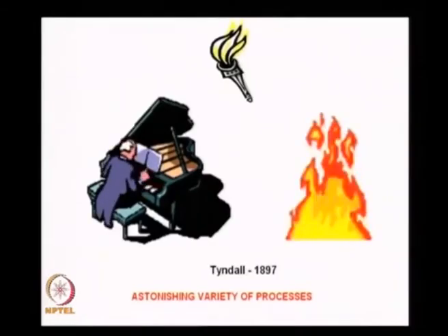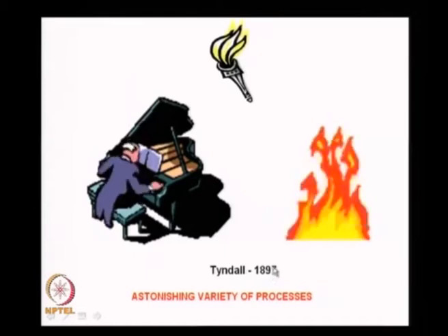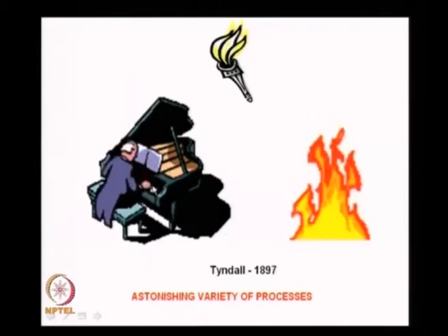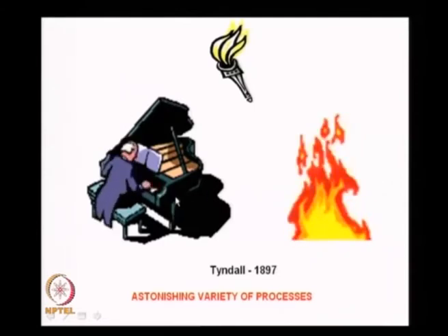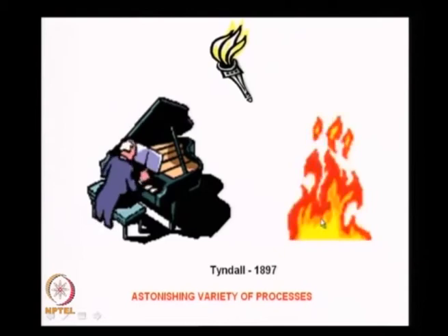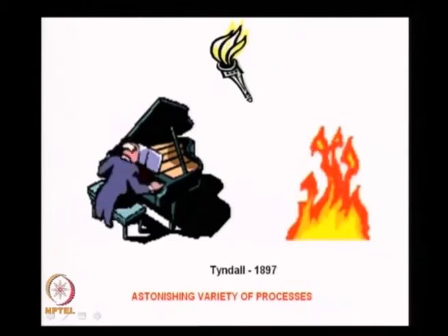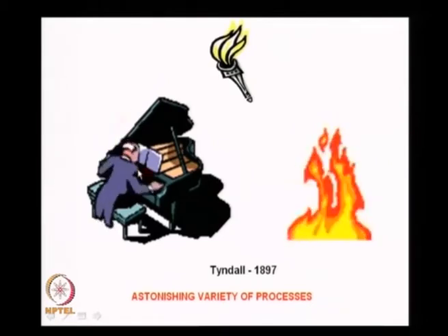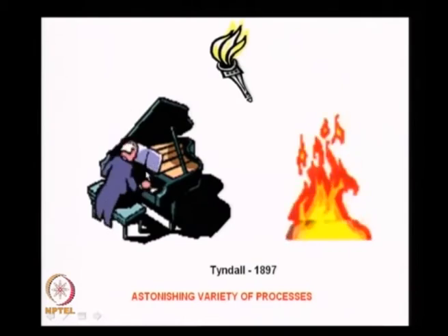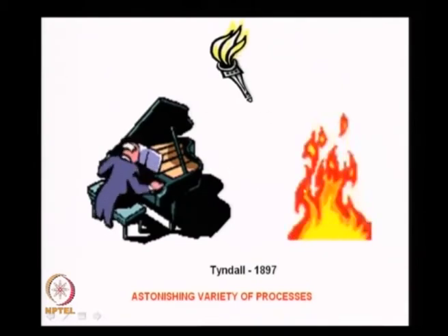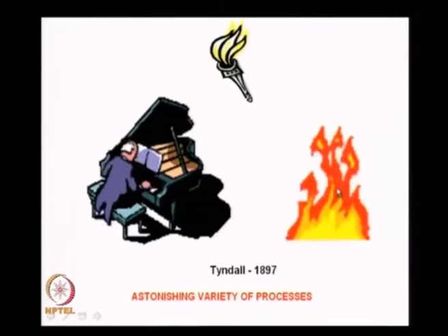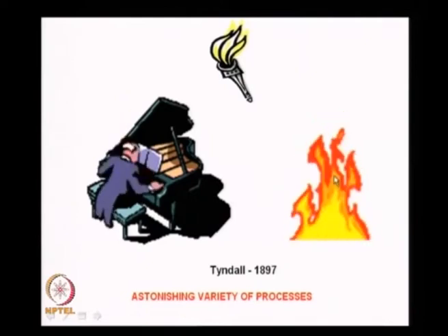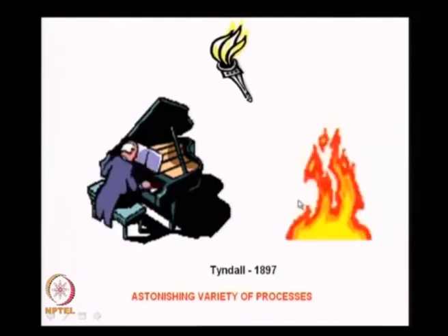This particular person, Tyndall, in 1897, demonstrated that when he struck the piano notes, the flame would just jump up, and the moment he stopped, it would come back again. But when the piano is not there, you would get a steady flame. In other words, the acoustics is affected by the heat addition, and that happens because the pressure perturbations are in resonance or in phase with the pressure or velocity fluctuations, that is, the heat release fluctuations.